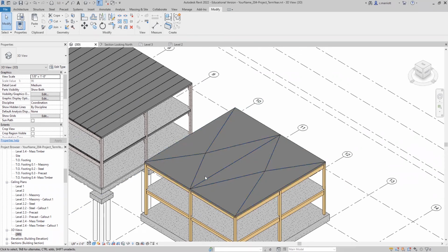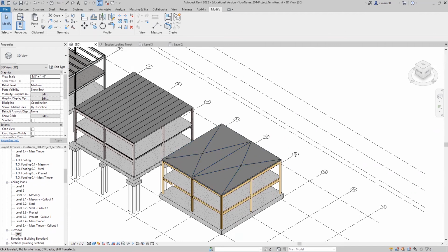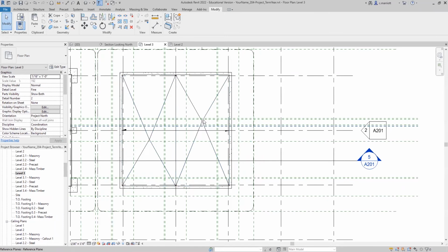Now, technically, when we use a 1/4 inch per foot insulation, the graphic for the top, if drawn accurately, would produce 45-degree angles coming from these drains.